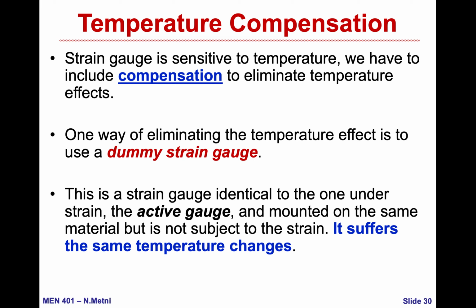So whenever there is an increase of resistance of the two, I can ensure that this is coming from the temperature. If the strain gauge on the cantilever beam changes, I can say that this is based on strain change, not a temperature change.